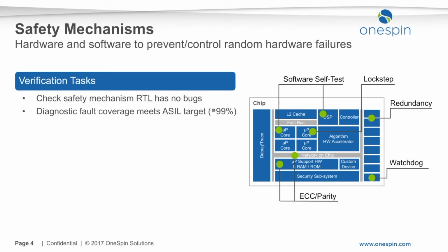For applications such as controlling the inflation of an airbag, the hardware may have to reach the ASIL-D target. That means that engineers might need to demonstrate that the hardware has a very high diagnostic coverage, as high as 99%. What are the challenges in performing these two tasks?